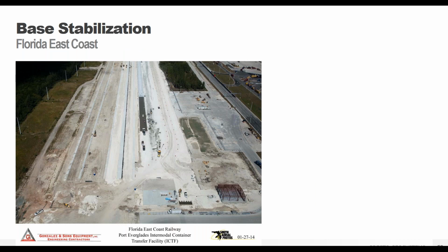This was for a facility down in Florida where they had a roller compacted concrete solution that they wanted some value engineering on. So this was at an intermodal yard that was going to have gantry trains, so really heavy loads. And part of the issue was that they were going to need to do up to 8 months of surcharge loading over the site to accelerate primary consolidation and protect against excessive settlement. And so, as expected, the long time frame to implement this preloading strategy was pretty unacceptable.